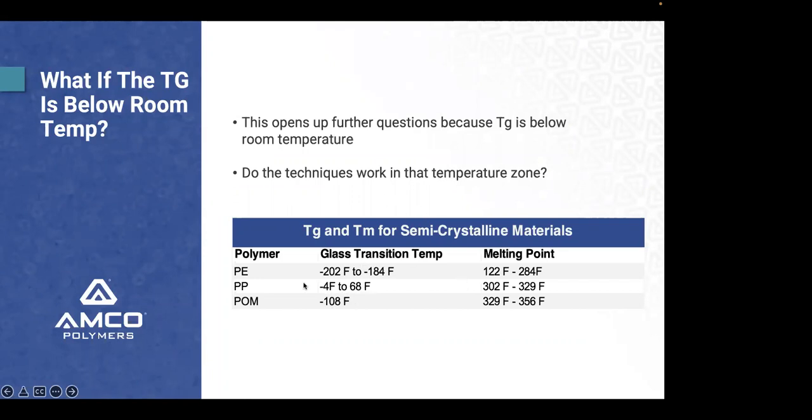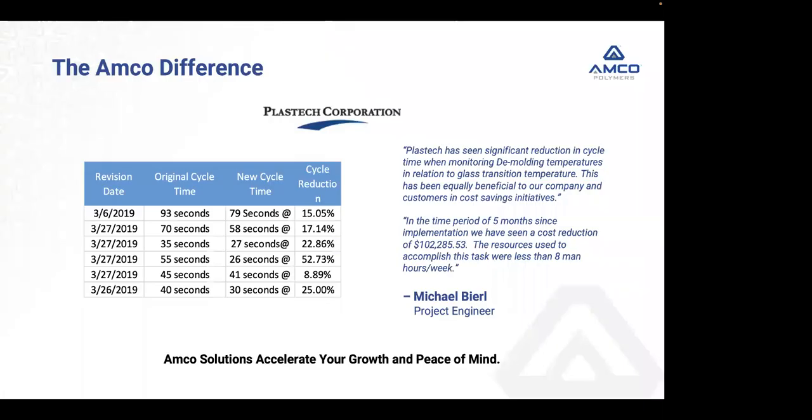So these are ones that we need to discuss more, and in future things I want to talk about polyethylene, polypropylene, TPO, acetal, but I want to determine the slope of these curves and know exactly what it is. I do know from Moldflow, when we've been doing different things, that polypropylene ejects at approximately 230 degrees Fahrenheit. We may be a little hotter, maybe a little colder, but right around 230, 240 degrees Fahrenheit, polypropylene can eject, starts getting soft, and you start getting hotter than that.